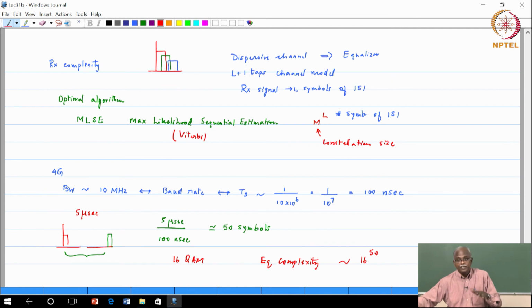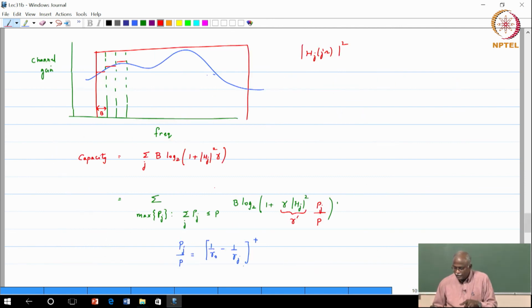Notwithstanding the fact that if I transmit a single carrier system, I am not going to achieve capacity, I am going to have a tough time because the frequency is not flat. So, does multi-carrier, splitting the carrier into smaller frequency bands, help? Because it helped us achieve capacity, right? Did it also solve the equalizer problem?